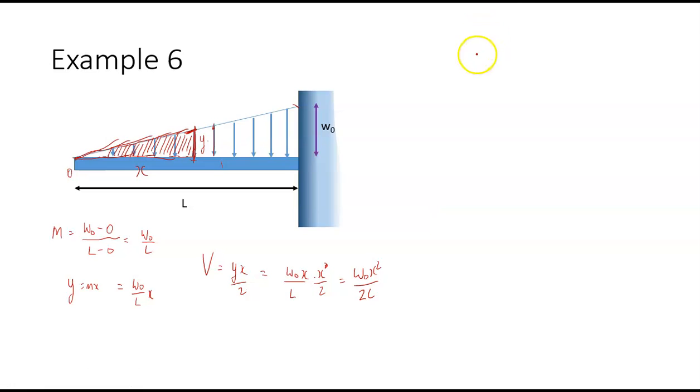If I want to get the bending moment, well, the bending moment would be the force multiplied by the distance. So if we take this point here, that force is going to act through the centroid. And that centroid there, that distance there, is 1/3 of x. So if this now becomes x, this distance is 1/3. Okay, so it's acting there.